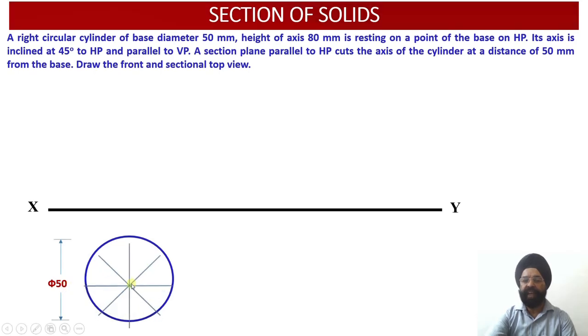And then we are going to work out the center point and divide this circle into 8 equal parts. So we have divided this into 8 equal parts so that every sector will be of 45 degree angle inclination over there. So this is 90 degree, you can see, and we have divided it into half. So each sector is equal to 45 degree. So let us do the numbering. 1, 2, 3, 4, 5, 6, 7, 8.